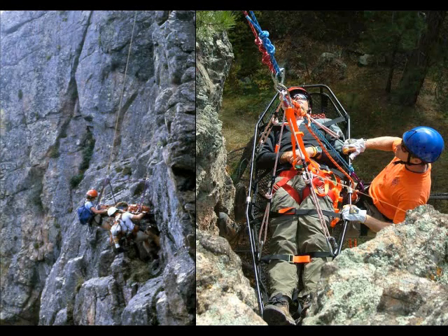Haul systems are much less efficient when there's a lot of bounce or when you have to pull a lot of stretch out of the rope with every pull. Here again, a static rope is going to increase your efficiency and it's going to improve your system performance.